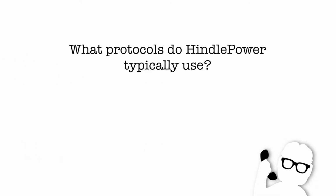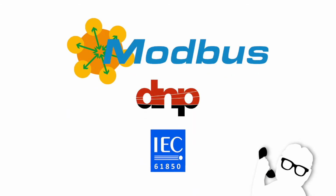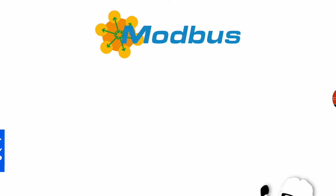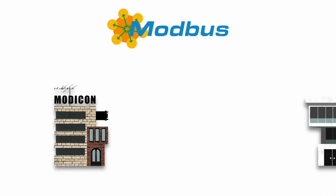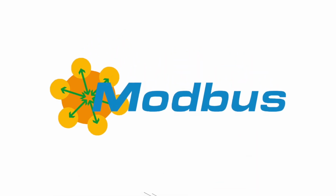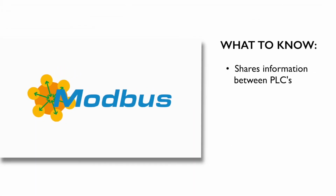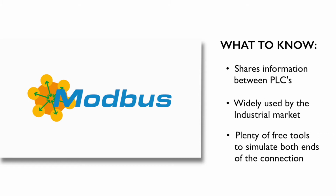And can you tell us what some of the typical ones are that we use? The three protocols we support are Modbus, DNP, and IEC 61850. Modbus was developed in the 70s by Modicon, which is now Schneider Electric. It's a simple protocol, and it allowed for a simple way for them to share information between their PLCs.